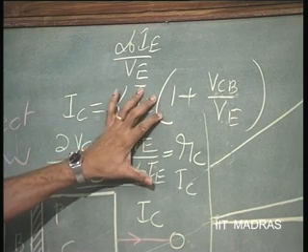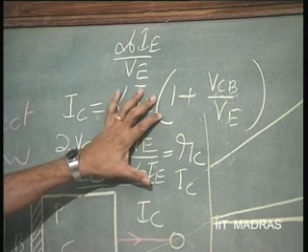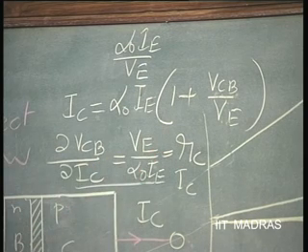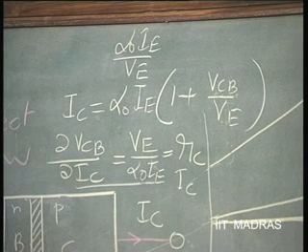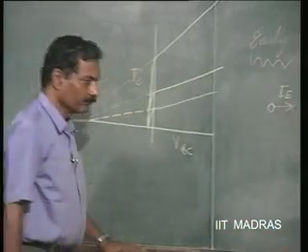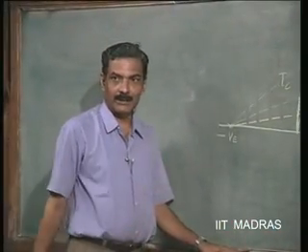If you are therefore analyzing your circuit using SPICE programs etc., you have to give the early voltage. Now, I would like you to compute the value of output impedance for the example that we have chosen, example 10.